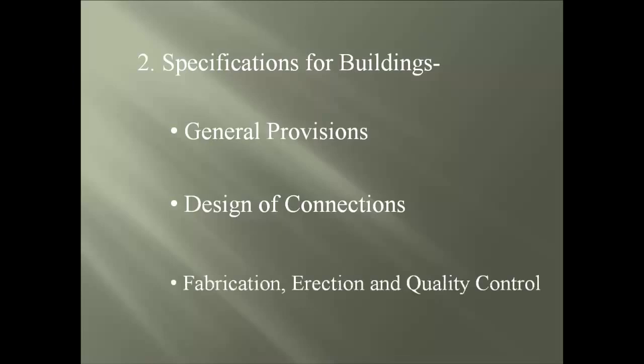And the last item is the fabrication, erection, and quality control for the shop. A quick tip is, both the shop and erection drawings shall clearly state the difference between shop and field welds, plus the pre-tensioned and slip-critical bolt connections. We first enter into the item fabrication, which covers camber, curving, straightening, thermal cutting, edge work, finishing work, holes, and galvanized members.